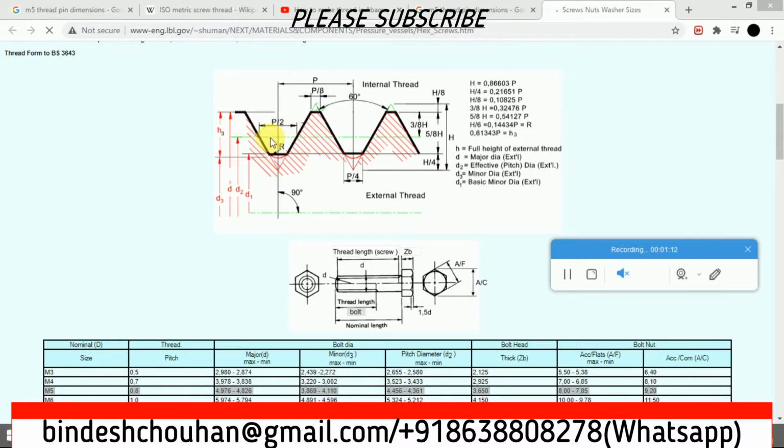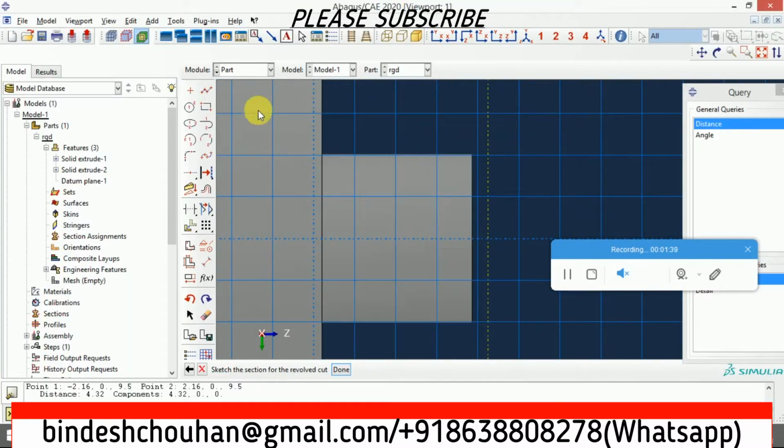The thread inclination is 60 degrees total, so half will be 30 degrees, and this line's width is p by 4. p is 0.8, which we have got from here, so it will be 0.2. So let us first draw a line of size 0.2.